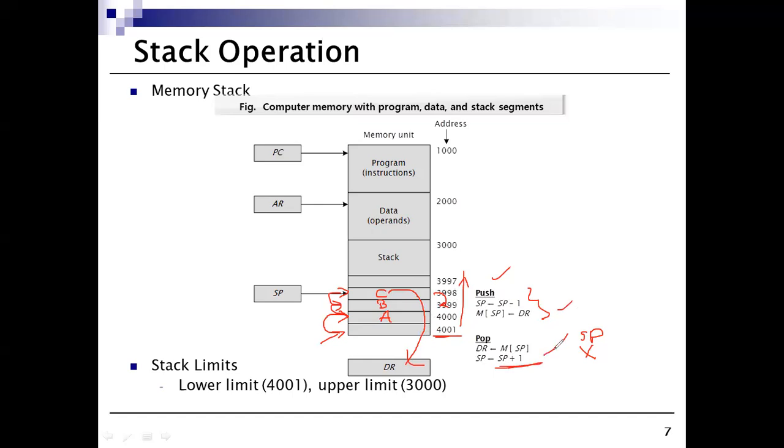In any case, we won't have any flag bits like empty or full in a memory kind of stack, which were available in the register stack. Okay, unlike the register stack, the memory stack doesn't have any flag bits like full or empty. We only have to see the upper and lower limits, which are available in some registers. You need to keep them in a register by which you can observe whether the stack reached full or else